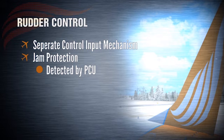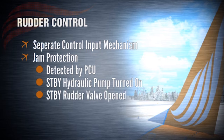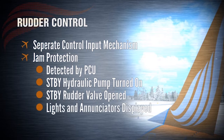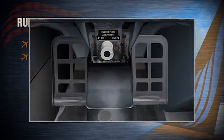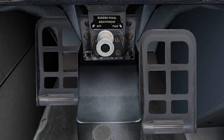It's important to understand this because the FFM, after 5 seconds, automatically turns on the standby hydraulic pump, standby rudder shutoff valve, and pressurizes the standby rudder PCU. Lights and annunciators are displayed in the cockpit when this condition occurs. The rudder has a maximum deflection of 29 degrees left and 29 degrees right.